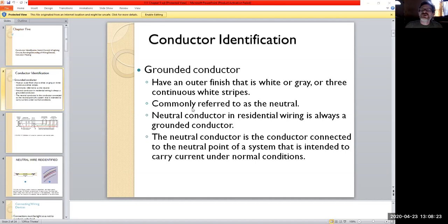So you always have black tape, but you have the colored tapes as well. I used to carry around a red, blue, green, and white, and then black, if I had a tape roll. The reason being is for identification. So if you had to use a black line for a neutral, what you have to do is at any point of connection where that thing is shown, you will loop wrap.